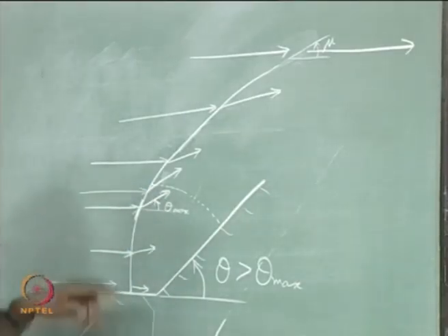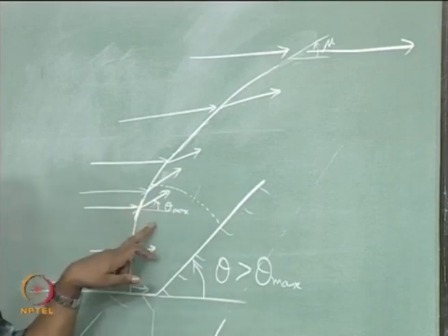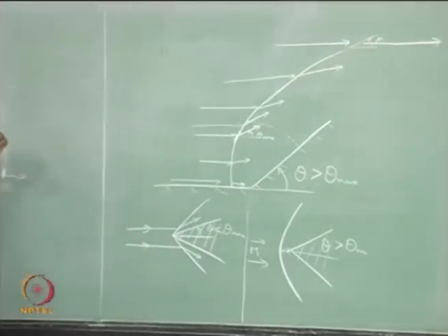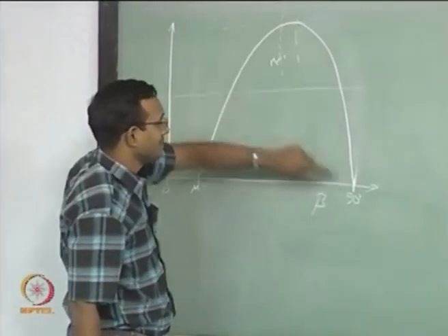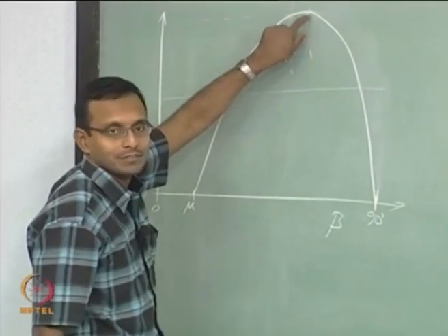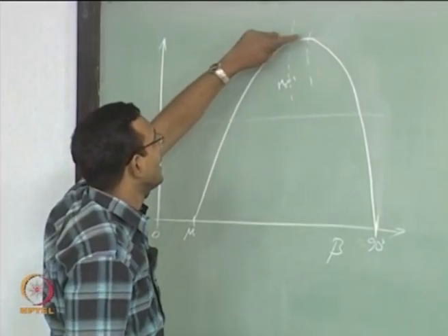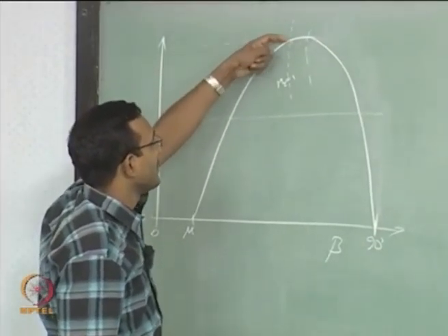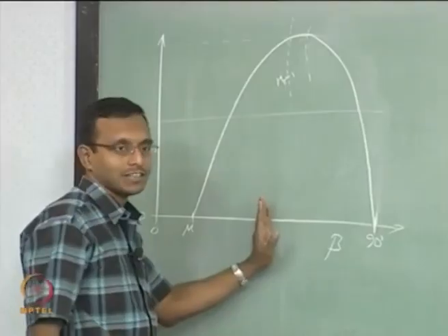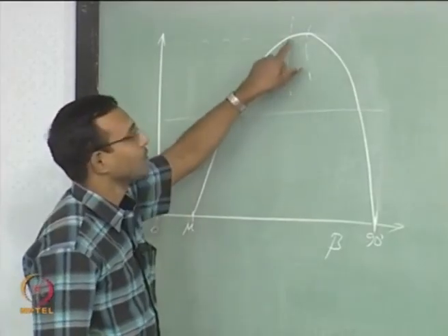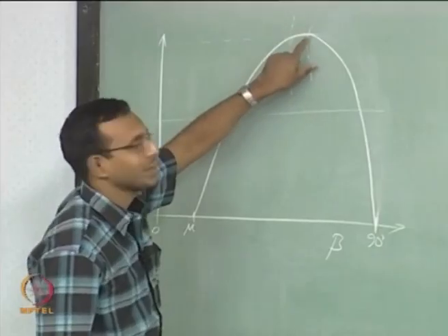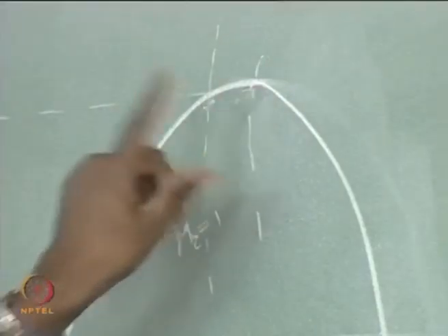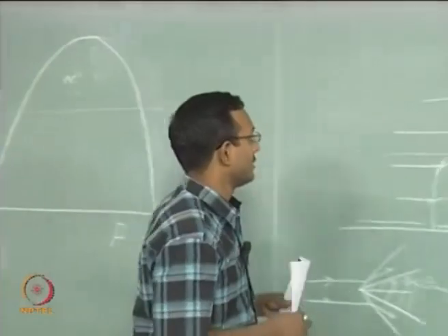Okay. Why am I saying that the theta max will be in subsonic range? We go back to the curve. Theta max is sitting in a point where M2 is subsonic. Okay. That is all I am saying, and slightly below theta max on the beta lower side is where you will have M2 equal to 1 happening. The only point where M2 equal to 1 touches the theta max is at M equal to infinity, we will not go there, okay.